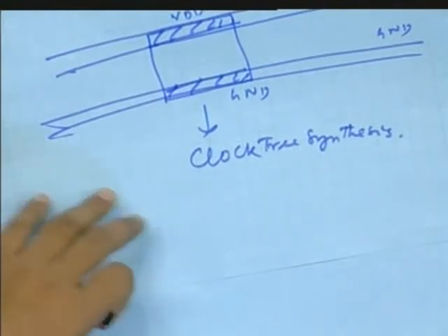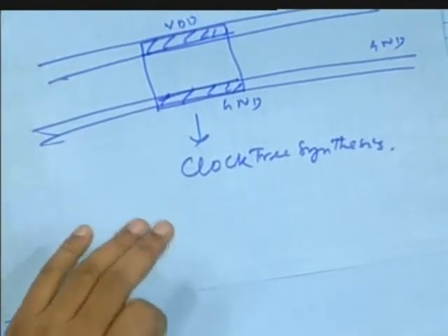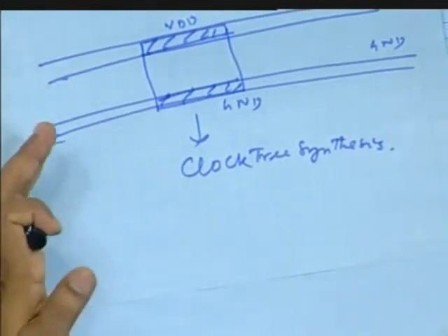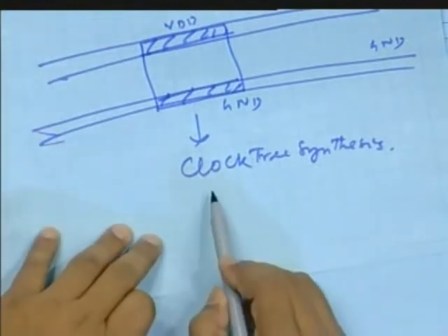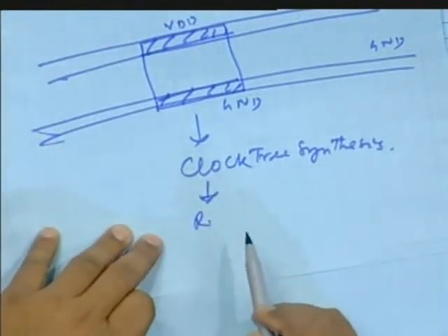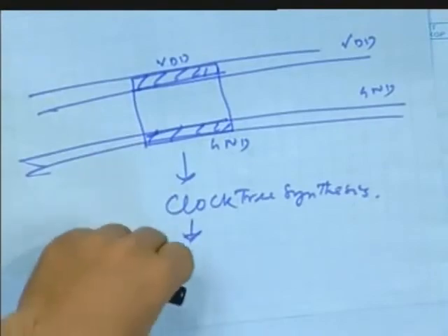Okay. Once clock tree synthesis means what? It's balancing the skews between different clock nets. I mean clock points where it is reaching the flip-flop clock pin. Okay. So once that is done, you go for routing. Actually, every time you do placement or routing, what you have to look for is the congestion map. Okay. Apart from that, there is the IR drop map.